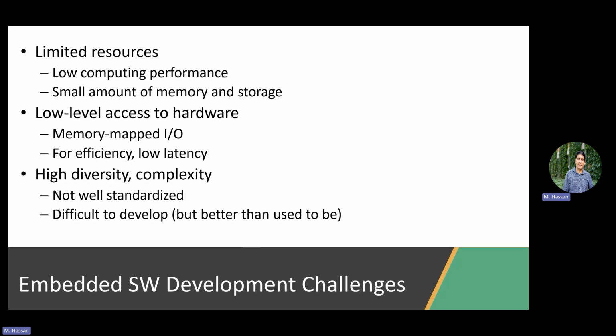So this diversity on the market, which is not the case for general purpose systems, makes it very hard to really write portable code, because the code that runs for your IDE in BEC is different. BEC is a different IC, so it's a harder example. But even in your second year, if you had an ARM core but a different platform than ST Microelectronics, like another Texas Instruments board, your IDE will be different. The way you write code will be slightly different, right? So it's very hard to really develop something that is standardized in an embedded system, right?